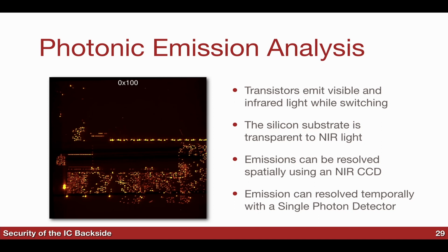In the middle, you can see where memory access is happening in SRAM, and up top is the actual address. Now I'm going to let this run. You can see the layout of different addresses on the device. And not only that, but you can find data-dependent parts of the circuit too. I'll let you figure out how we know this is data-dependent.